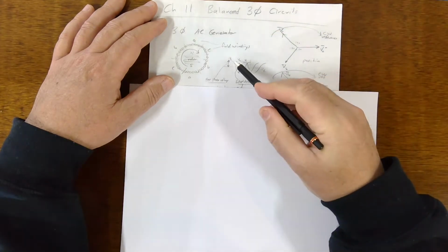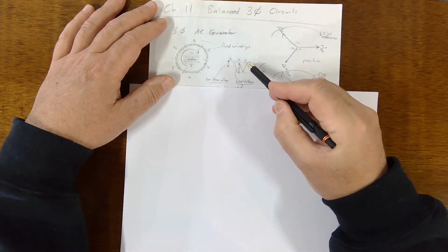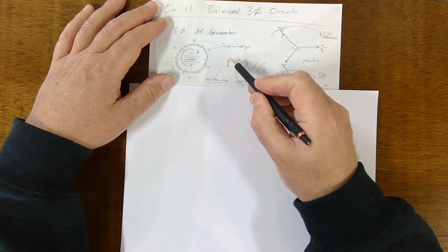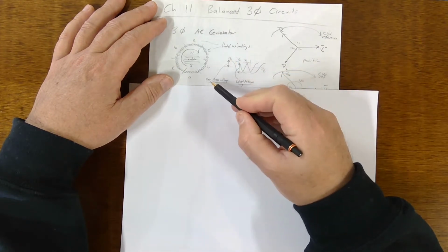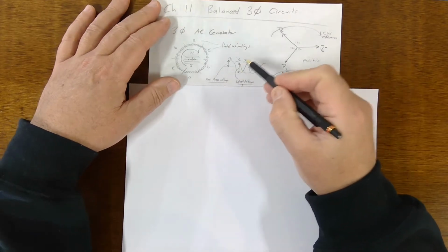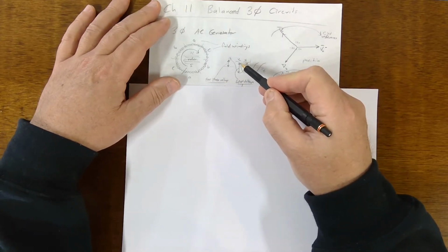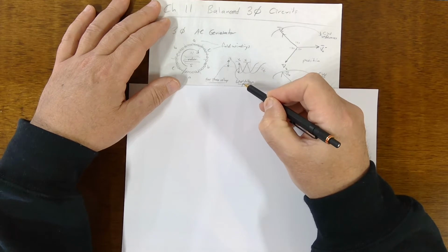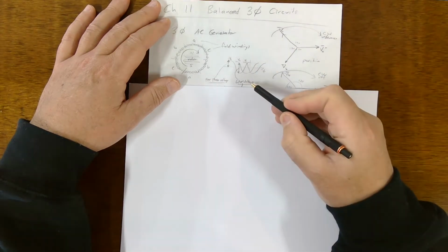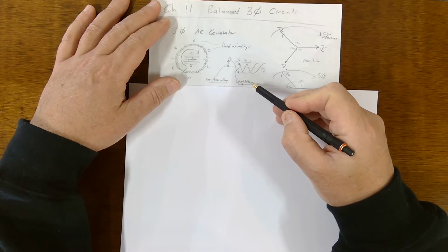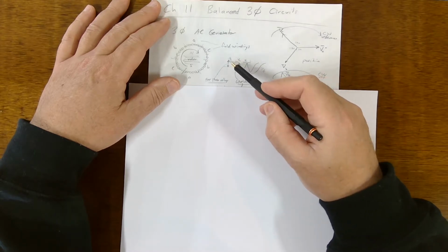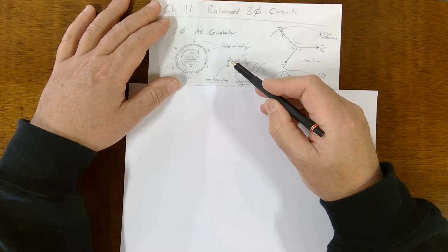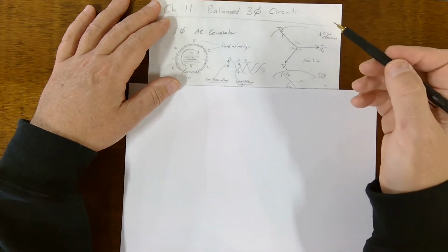So they look like this. They all have the same amplitude, but they're out of phase by 120 degrees. And if you take any given signal and go from peak to neutral, we call that the per phase voltage. And if you take any two phases and go from peak to peak, we call that the line voltage, or sometimes the line to line voltage, which I think is a more descriptive term. For line voltage, use the term line to line, and for phase voltage, I like the term phase to neutral. I think that's more clear.